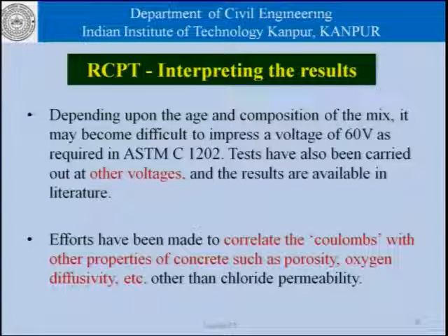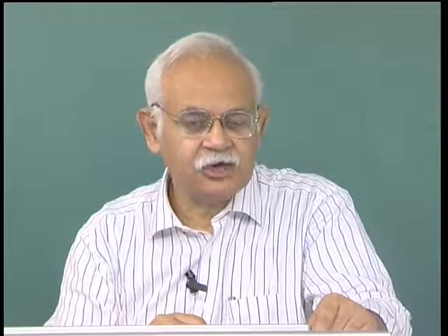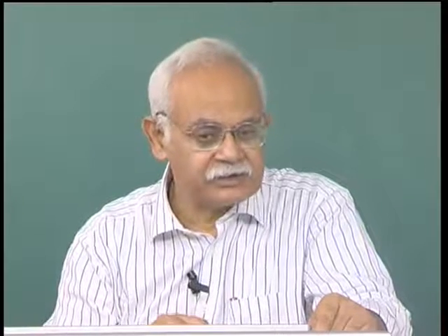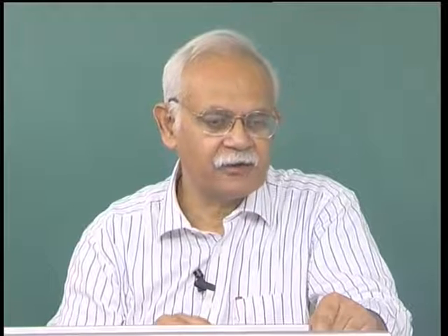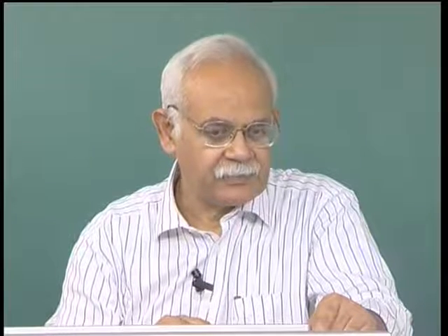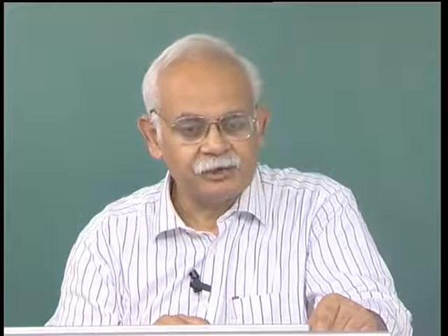Effort has also been made in literature to correlate the coulombs with other properties of concrete, such as porosity or oxygen diffusivity, strength and so on, because at the end of it what we are trying to measure is related to the porosity. It is not porosity itself. Porosity itself is measured in terms of volume of pores in a given volume of concrete or in a given mass of concrete, but the diffusivity is also related to the porosity.